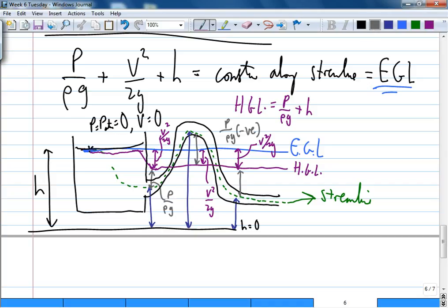You would think here is P over rho G. But I realize, hang on, your pipe opens out to the atmosphere already. So your P over rho G must be 0. So that part I drew the pipe wrong. By right, if this was still the case, the pipe should exit here, should continue a little bit and exit here. If not, it doesn't make sense.